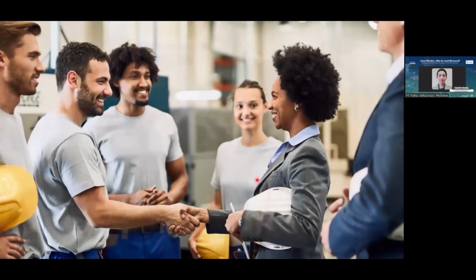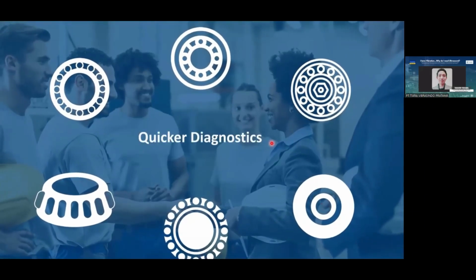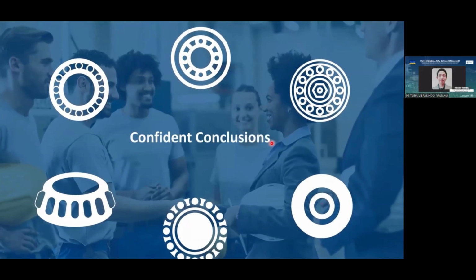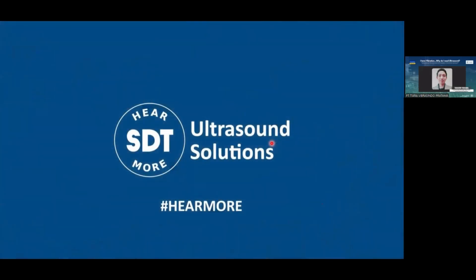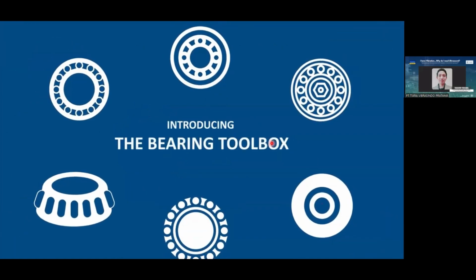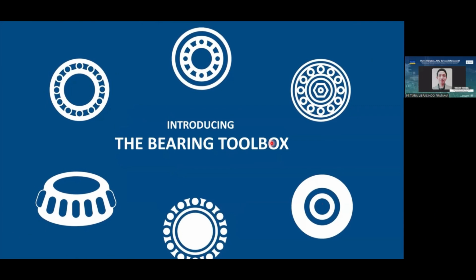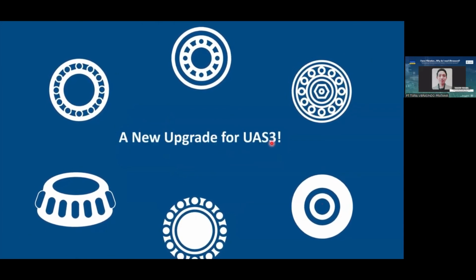So it's very simple for the ultrasound software. You don't need an expert. It's like vibration analysis, but you just need to know the correct bearing model or bearing manufacturer. Just select that and pinpoint to the data that you collect for the time waveform or spectrum.